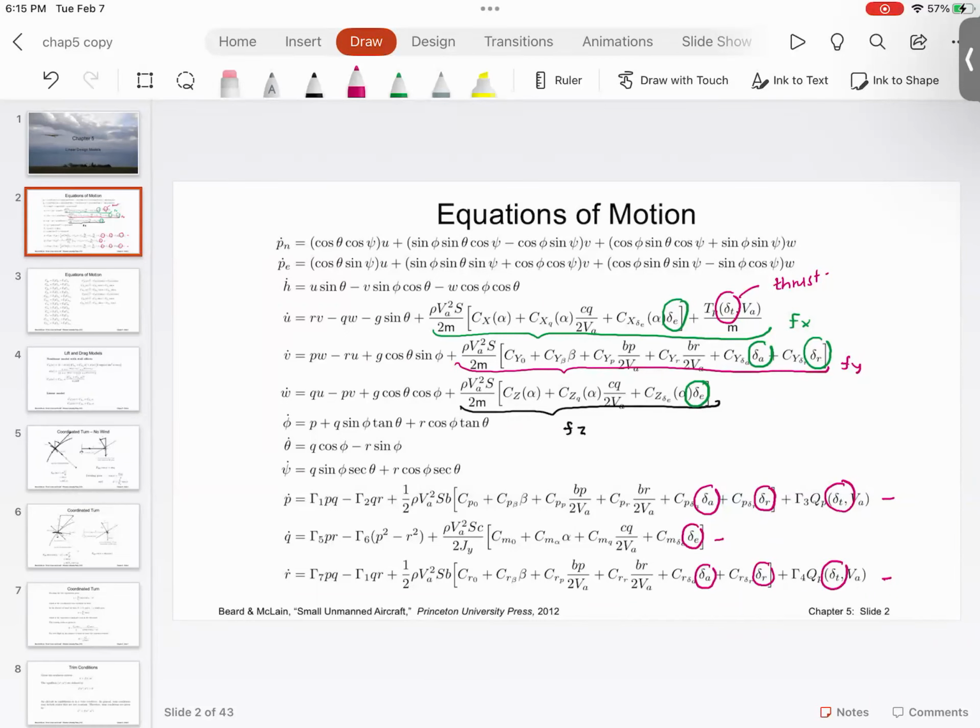Even though these equations or these functions are non-linear, in a very small operating region, those can be approximated as a straight line. So even though these differential equations are complicated and non-linear, if you take a very small snapshot of the trajectory around the operating point, you will notice that the behavior is linear.